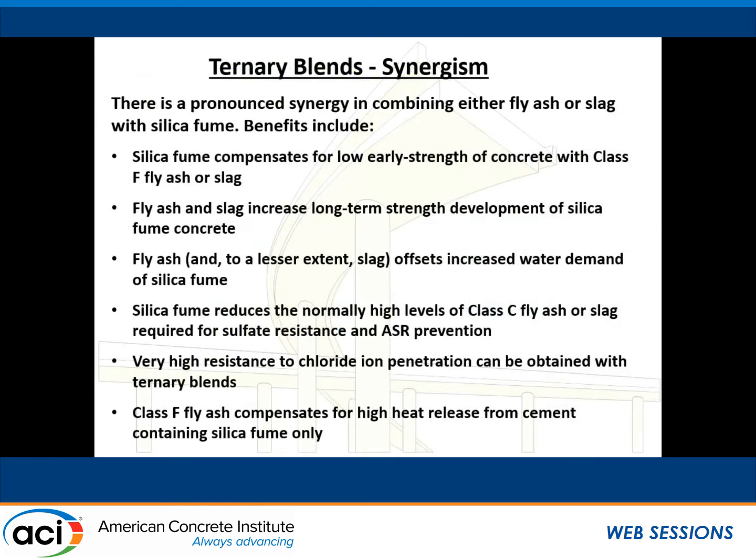And I think Jan touched on some of the synergistic effects. We particularly see synergism when we take a fast-reacting pozzolan, like silica fume or metakaolin, and we put it with a more slowly reacting material like fly ash or slag. We get the benefits of both materials. We get good early age performance, but we get later age performance too. And hopefully from these very old slides, I'm going to be able to demonstrate that.